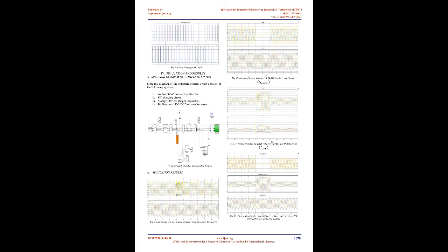B. Analysis of TCR. The thyristor controlled reactor is a self-controlled device handled with the help of many thyristors. The operative reactance is attainable by controlling the firing angles of the thyristors within a firm limit. One pair of thyristors in the TCR is applied anti-parallel. Both thyristors conduct due to the pulse applied to the gate input in either the positive or the negative half cycles of the voltage supplied to it.